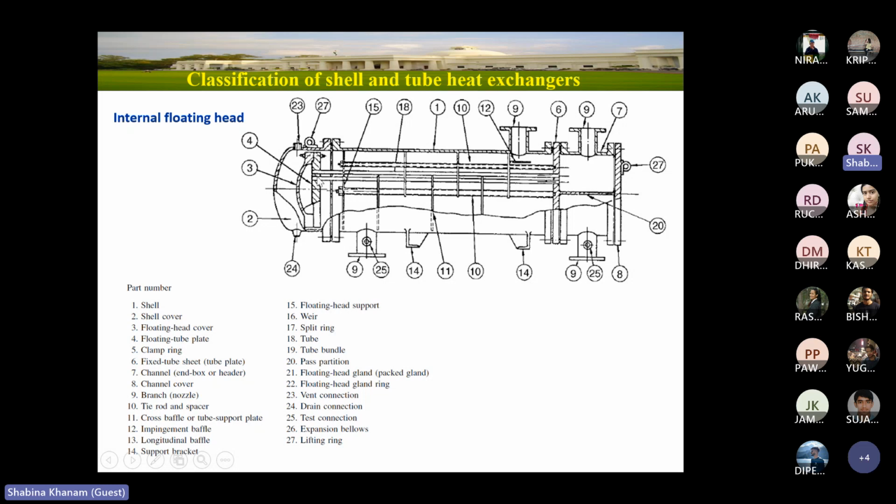And as bending is not there, the tubes are straight, which is very easy to clean. You can consider this type of heat exchanger to handle fouling tendency fluids as well. So the limitations of the fixed tube sheet and U-tube heat exchangers can both be handled over here. This is a win-win situation, everything we can accommodate over here.